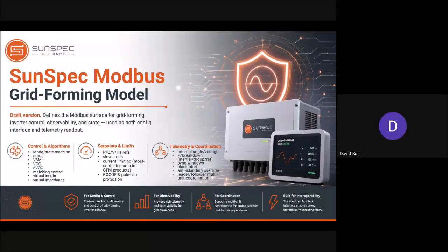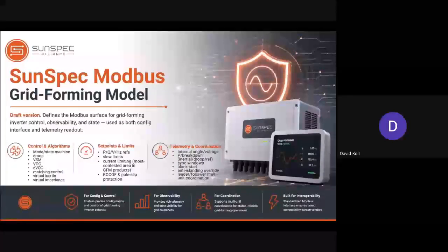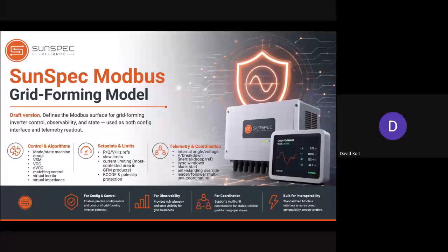It's also exposed the weakness in the power distribution capability when the grid is non-operational and all those DERs just sit in an idle state waiting for the grid to return. This has raised the question of what do we do when the grid drops out? When the grid drops out, the grid following system, by design, senses that the grid's dropped out and is ordered to cease to energize, or cease to export power. Said system is required to turn itself off to avoid creating an island, or in other words, provide anti-islanding protection.